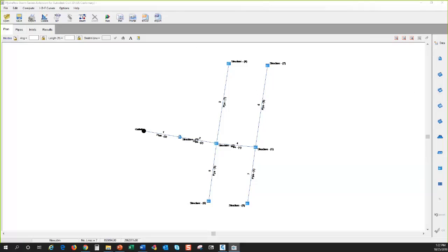You've got information here when you select one of these. You can see the angle, and that's the angle from the last line, and then the distance, the length, is here. You can edit these here. You can lock them. So when you're in here, if you wanted to manually adjust this, that's not the preferred workflow. It's better to do this in Civil 3D, but you have the ability to do it in here. And if you select another one, you can see it changes to the angle and the distance to each line.